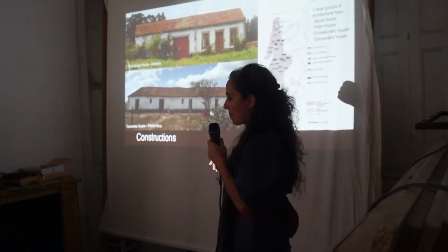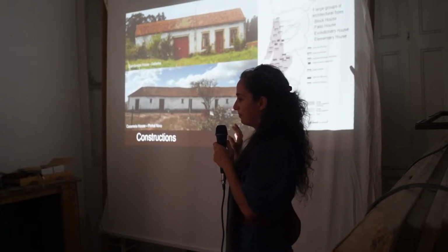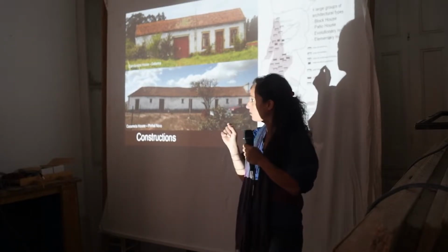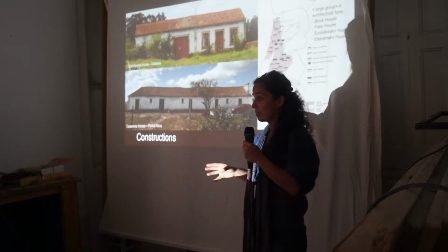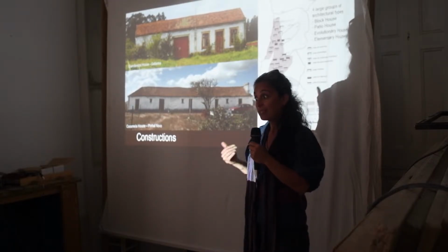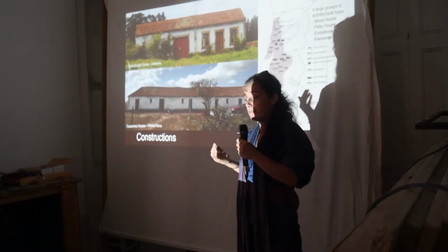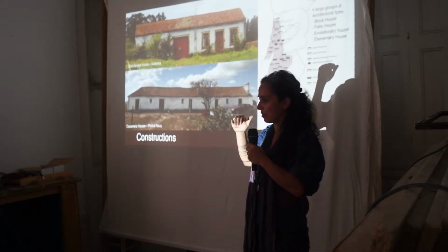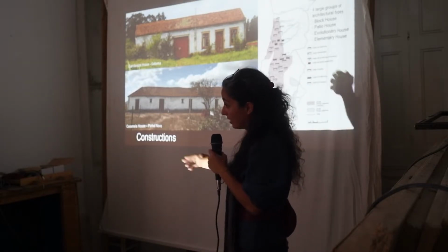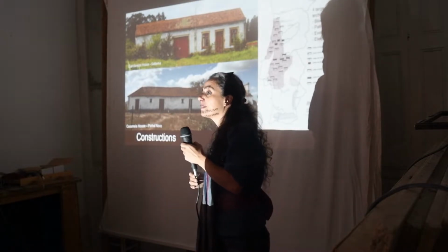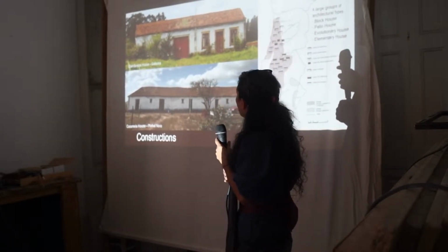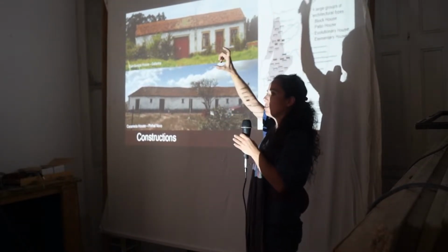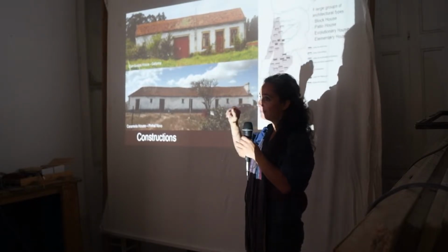How does it work with stone? There's no stone there. Normally, in some places you have a foundation made of stone, because you shouldn't use earth in the foundation. But sometimes you can, okay? But it's not the best way. So normally they make the stone foundations and then you go up and you make the earth construction, okay? Tell me. I was going to ask what surrounds the basement window? No, how it's done. So you make the walls, and then only above you have timber, okay?